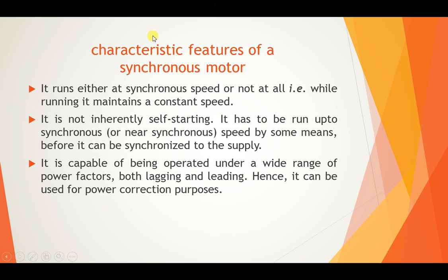There are a few characteristic features of synchronous motors. It runs either at a synchronous speed or not at all. That is, while running it maintains a constant speed. As its name implies, it must be run at a synchronous speed or not at all. So it is not inherently self-starting. It has to be run up to synchronous or near synchronous speed by some means before it can be synchronized to the supply.